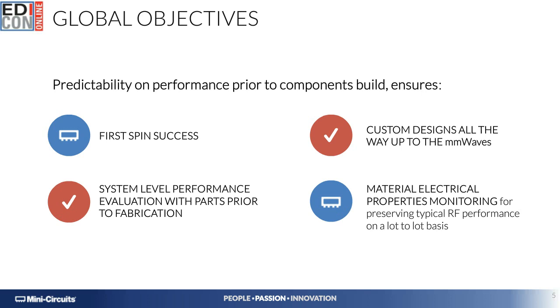At the same time, we also recognized that any design at those high frequencies would pretty much constitute a custom design. As previously mentioned, this is given the complications added by working at these frequencies, where the performance of the components is so much linked to the motherboard substrate stack-up, launch designs, surrounding elements, radiative losses, fringing fields, just to name a few of them.